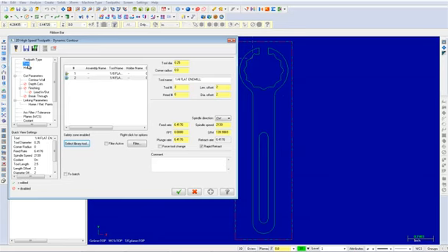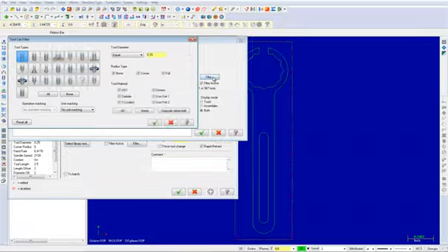From here we will select the 1/16 inch tool. To do this, choose the Select Library Tool button and then the Filter button. Now choose the None button and then under Tool Types, select the flat end mill icon. Next, under Tool Diameter, pick Equal and input a value of 0.0625 as shown. Once complete, select the OK button to exit the Tool List filter.